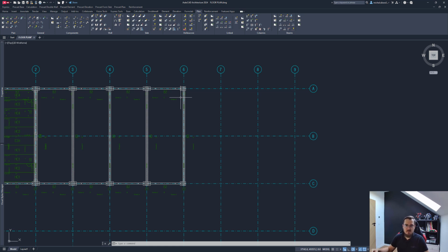And with that, let us go ahead and start actually working with sandwich panels. We'll create a small building on the side of that big storage facility or factory of sorts. So under the Walls tab, basically what we'll do is we'll click on the create or draw wall icon, and we'll select what type of wall we want to create. For me, I want to create sandwich panels. And like that, I can immediately start placing sandwich panels.